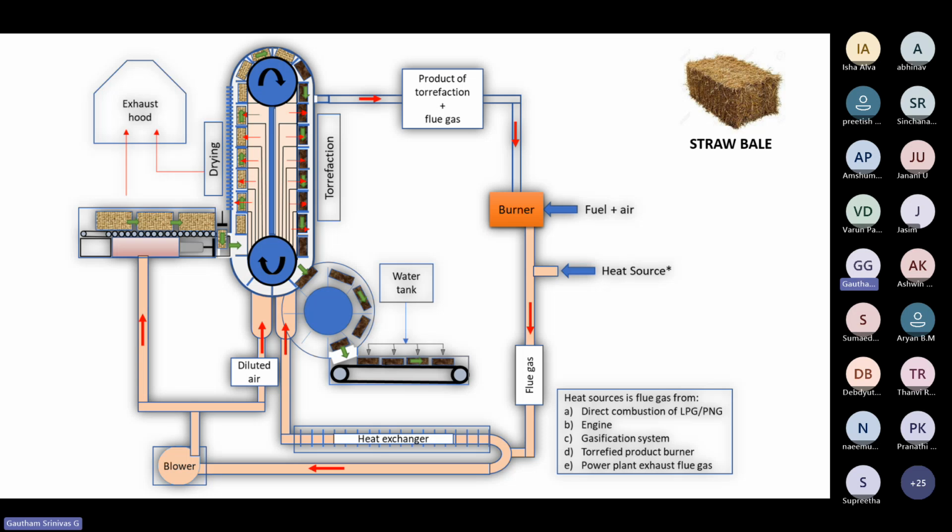Okay, and they are actually cut, right? They're sliced, basically. There is a plunger setup here that pushes this down, and then there's another plunger here that pushes it. It's pneumatically operated, and then it is pushed onto the conveyor. The conveyor is rotating this way. So on the left side you have a drying zone, and on the right side you have the torrefaction zone.